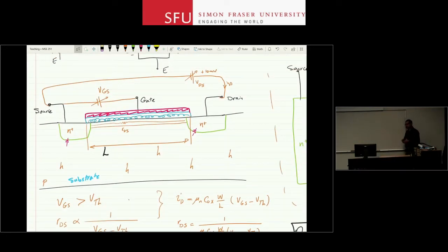So now we have a variable resistor, a great device. It's a resistor whose value is under your control. You can use it in all sorts of applications. If you notice, a lot of the electronic devices nowadays, instead of having a real knob, a real potentiometer to change a value, have a virtual knob. You move a bar up and down by hand, and how does that work? If it is changing an analog circuit somewhere, chances are that they're changing a resistor using an electrical voltage.